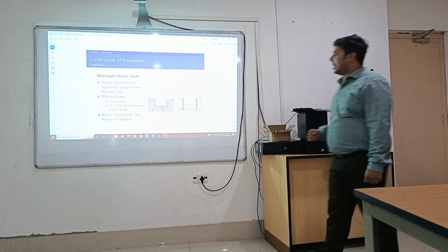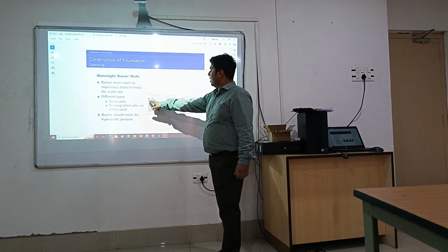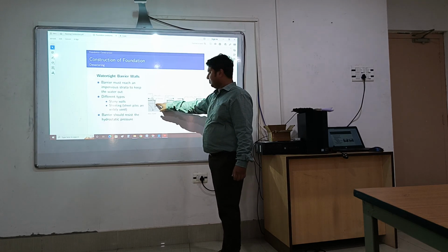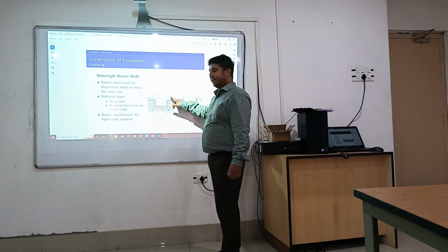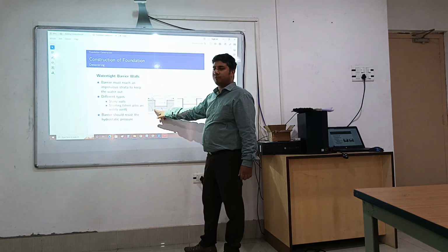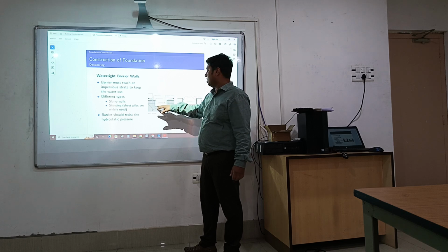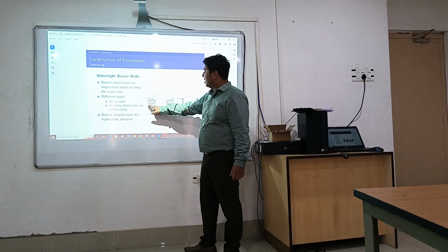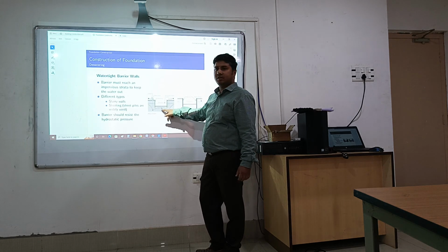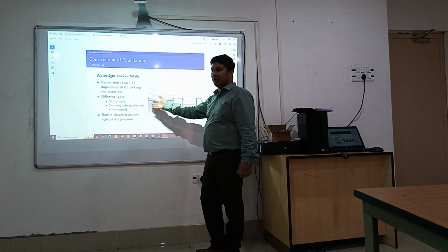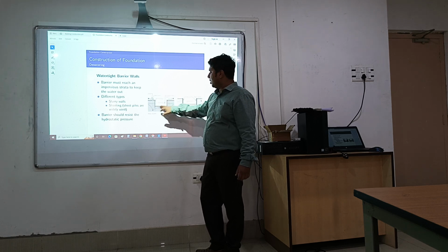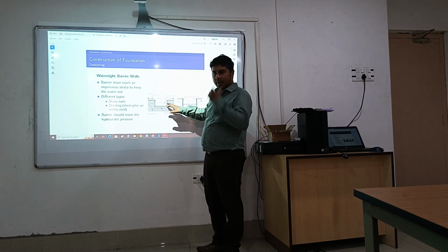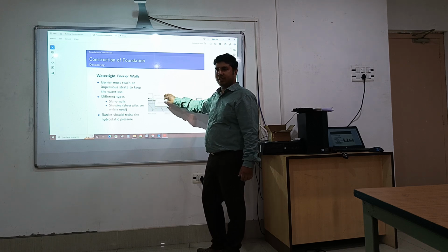We can also use watertight barriers. As you can see, suppose there is a pumping system, and this is the water level. We have done our sheet pile work for protection against caving, and we have also provided some watertight barriers. All parts are sealed, and this is the seepage. This graph shows that the water is not able to percolate inside the sheet. So this is how the space has been kept dry by diverting the water. There will be no seepage through this barrier, and the place where the construction will be done will remain dry.